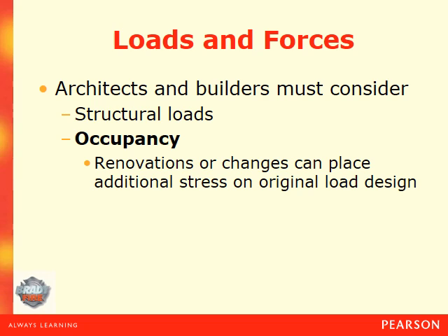Renovations or changes can place additional stresses on the original load design. And that's one of the big problems in the fire service in terms of building construction. You may have older style homes that have been updated, and you may not be aware of said updates unless you've been in that type of structure.